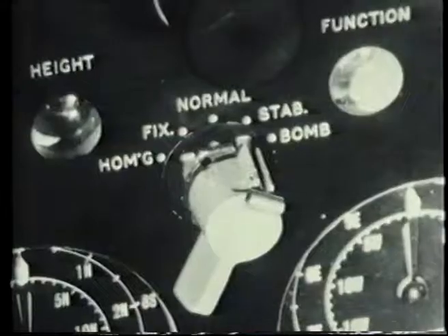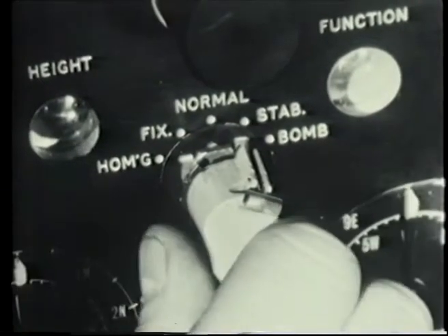If the aircraft is flying in this direction, the picture on the PPI display will move like this. By applying to the deflector coils of the PPI shift currents that exactly oppose this motion, the picture of the ground can be made to remain stationary while the center of the scan, shown here as a white dot, traces out the path of the aircraft. This is known as the stabilized PPI display.